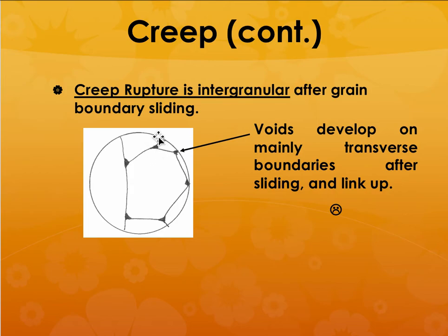And at the corner of the grains, you suddenly start forming a void. And not only that, at elevated temperatures, these grain boundaries suddenly become extremely weak. And they become like, suppose you take ice, okay? If you start melting ice, those edges of the ice cubes become extremely soft and smooth.